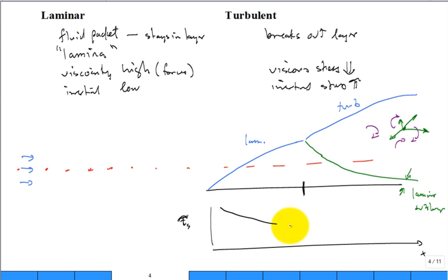It's going to go down, but then it kicks back up and then goes back down again. Initially there's a boost and it's higher in the turbulent region. If you wanted a large drag force or a large convection coefficient, you'd want to make it turbulent. The laminar part is like a layer of insulation, a layer prohibiting the flow.